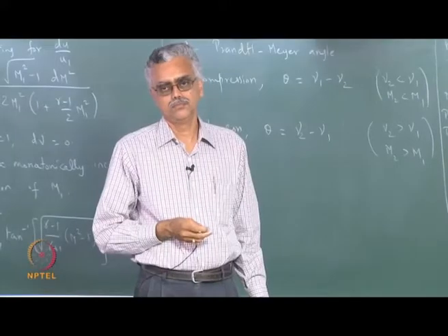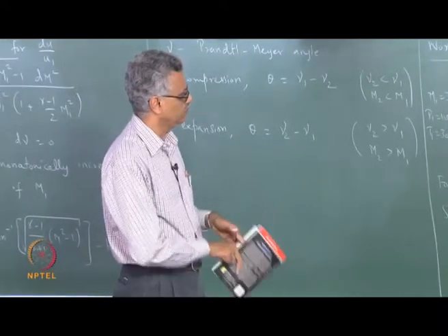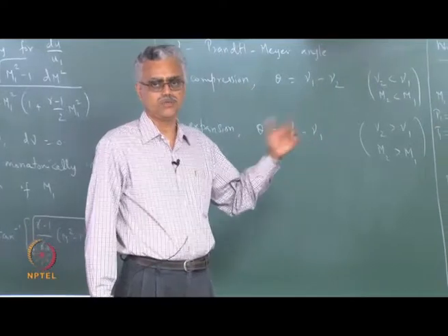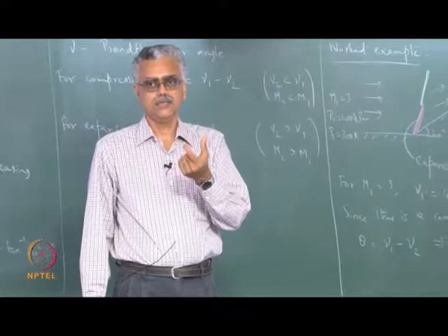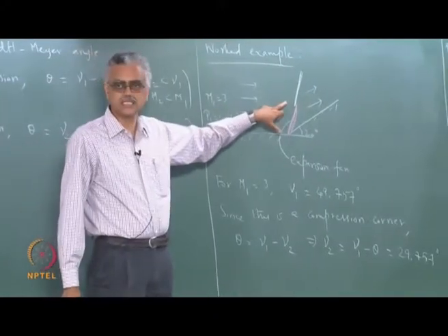But both the floors have the same angle, no? Means the deflection angle is the same, no? For isentropic also and for oblique shock also. In oblique shock, then P2 should be higher than isentropic. But you are looking at the compression taking place in different frames of reference. The normal shock compression for the oblique shock is only for the Mn1, and although M1 is equal to 3, this one is less.